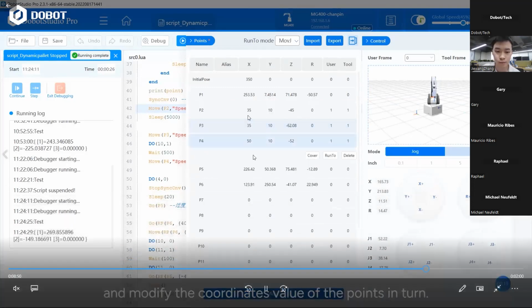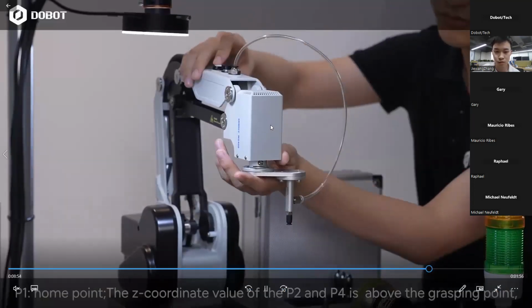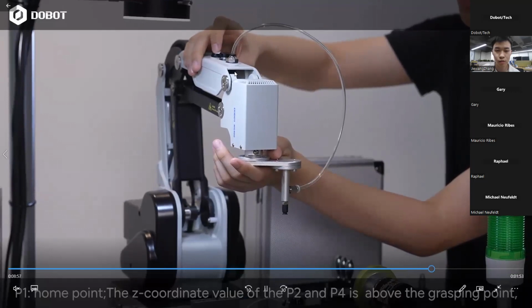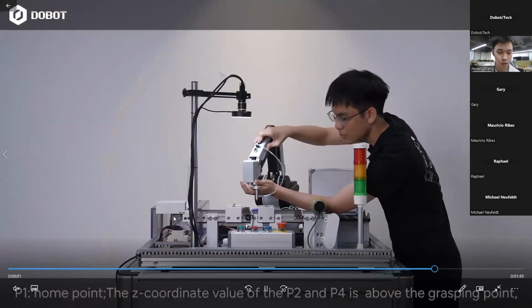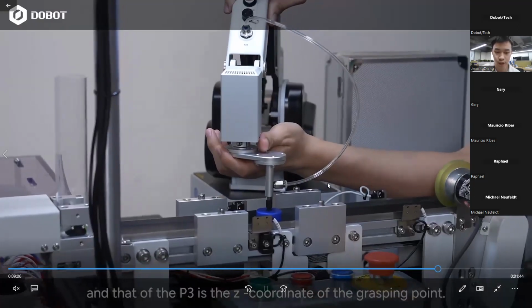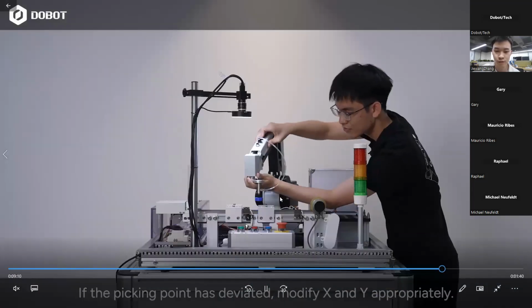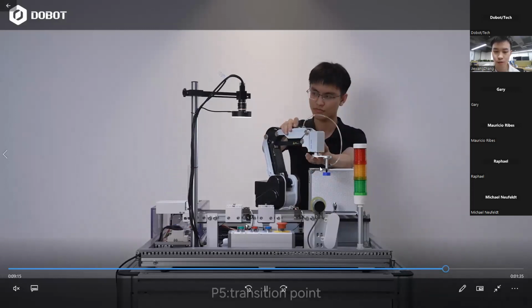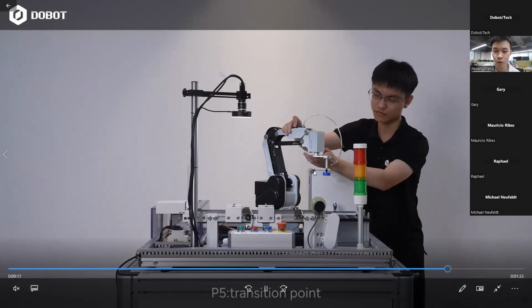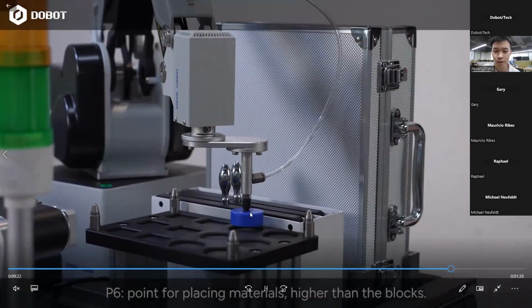In this case, firstly, we need to teach the Z coordinates of P2, P3, and P4, and teach P5, the transition point, and P6, which is the first point of the placing.